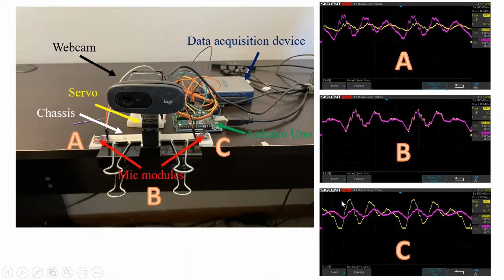So in order to tell where the sound source is, first I used cross-correlation to measure the time difference between the two sound waves, and then I do calibration. Calibration means I put the sound source at different locations on purpose and measure the time difference for each case and record the information. In real application, I just measure the time difference and do the interpolation to extract where the sound source is. In terms of the technique cross-correlation, I found this video has good explanation. You can just watch it there.